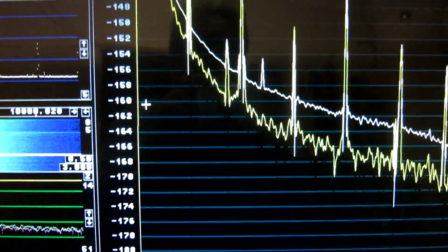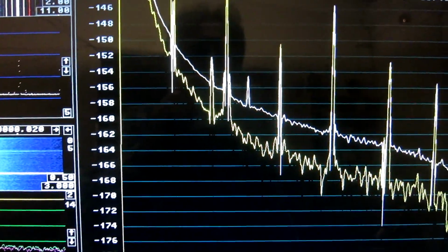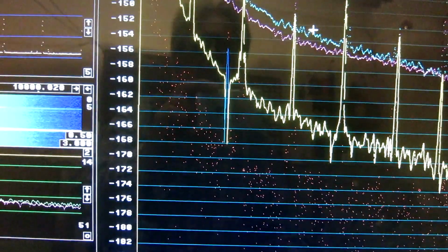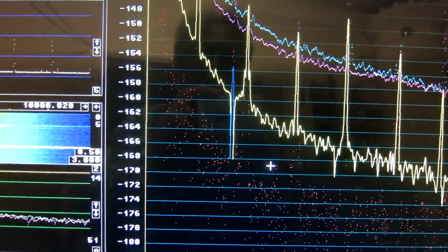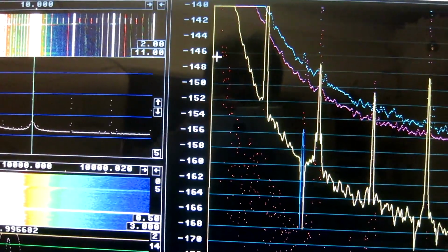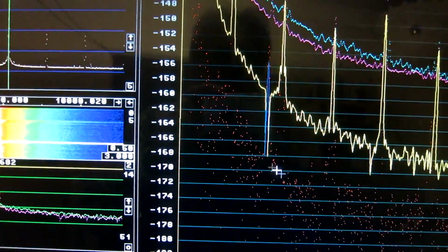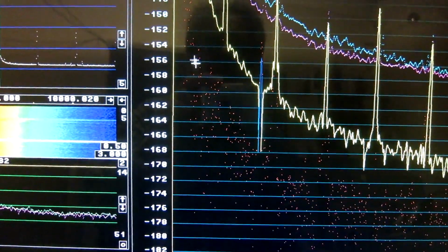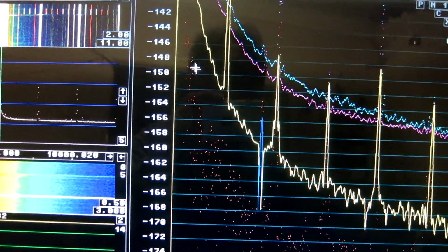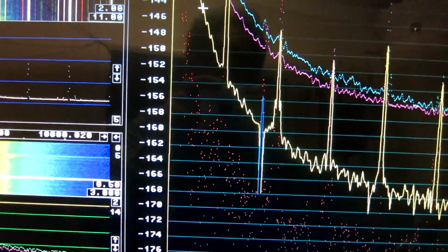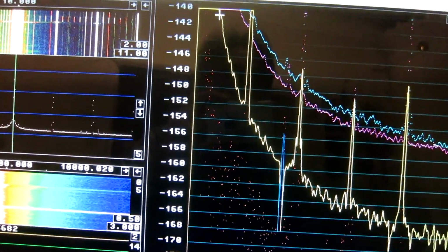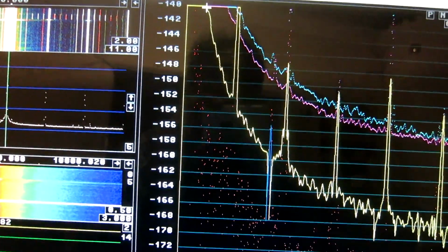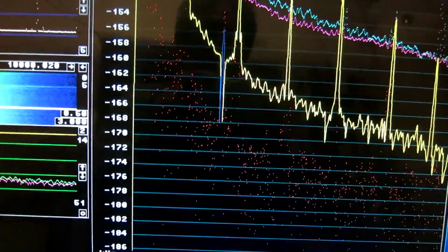But I shift now to the other display kinds. Here is the phase noise information, and we can see that the random noise from my receive system is well below the phase noise of the unit I'm testing. So this curve is correct all the way up to 10 Hertz or something.